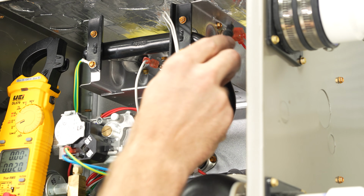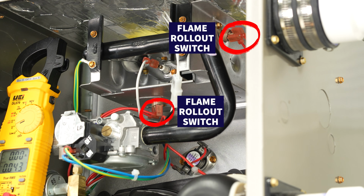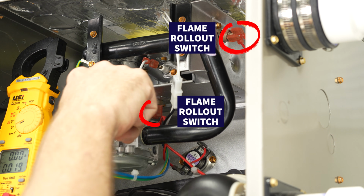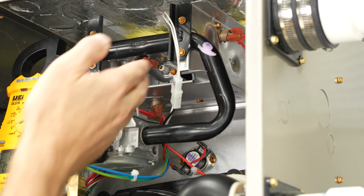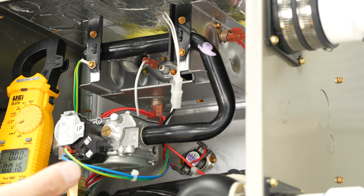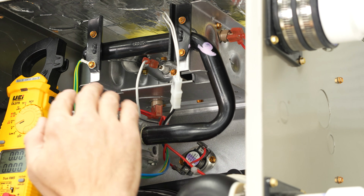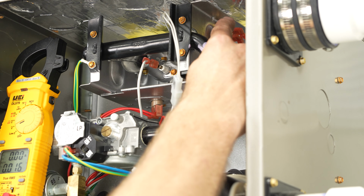So right back here we have a flame rollout switch and another flame rollout switch, and that is if the flame back here is popping towards the front. And it should never do that, because if you have a crack in the heat exchanger, maybe it would allow the blower motor to push the air through the heat exchanger and pop back over here. That would be a very serious problem, and that's why these flame rollout switches do not auto reset.